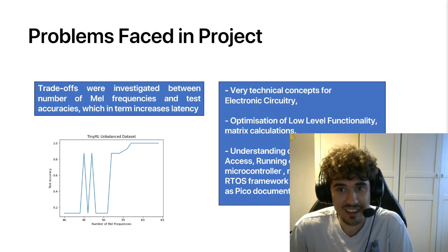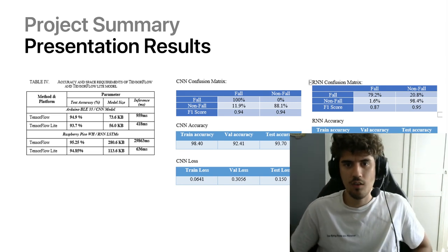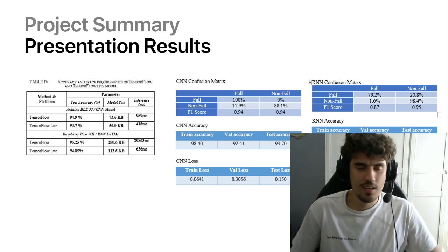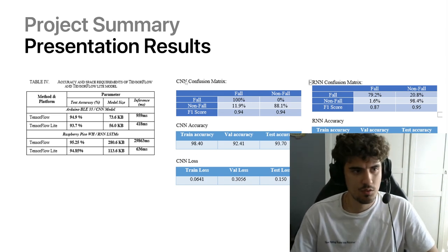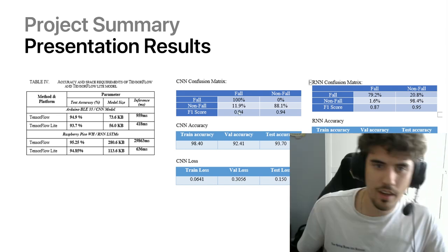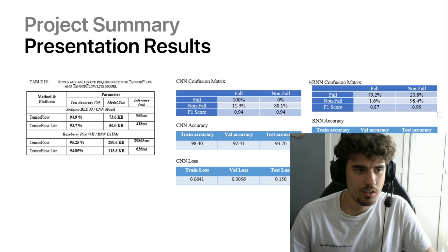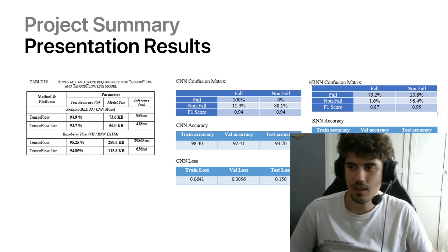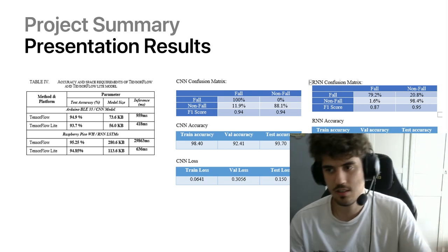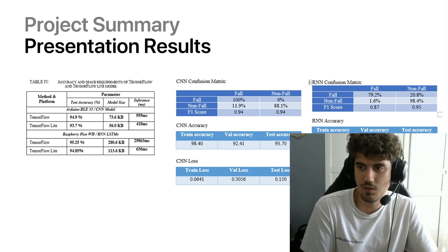So to conclude the project, I ran 2 different models, a CNN on the Arduino BLE and an RNN model on the Pico 2. The CNN showed quite good results, as shown by the CNN confusion matrix, roughly an F1 score of 94, with manageable latency and memory usage. However, due to the complexity of the problem, with things such as steps being similar to the sound, the CNN could not capture this difference, and so a more temporal-oriented machine learning solution was needed.